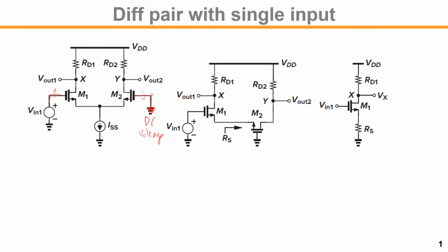Here again, if you only change the voltage on here, that will result in current variation ID. Such current variation can only go through M2. There is no other path to flow. So once there is ID there, then the voltage drop will be ID over gm. Another voltage drop, source and gate, would be ID over gm.